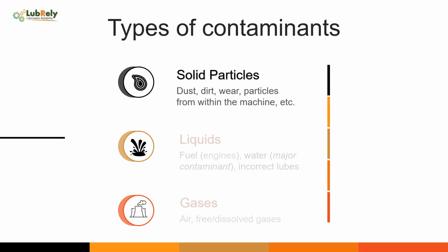Types of contaminants. When thinking of contaminants, the first thing we think of are of course the solid particles. Particles coming from within the machine. They can be very damaging because they are very hard. Think of iron, from casting steel, bronze, many pumps use bronze, and aluminum. Maybe you wonder how contaminants achieve such large and drastic effects. Thing is, contaminants can be irregular in shape. They have sharp edges, which cause abrasion as they scrape metal surfaces, which in its turn, create additional contaminants.